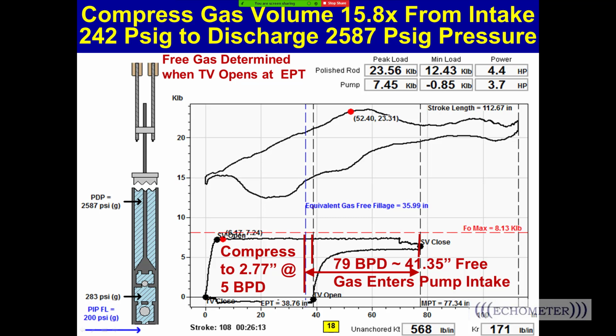That doesn't affect the calculations. Sand is just going to be part of the calculation at the pump. So let's say you make 5% sand, then the liquid volume you calculate at the pump, adjusted for stock tank conditions, should still be 5% too high, because there should be some sand volume that was inside the pump and it was assumed to be liquid, but it wasn't. So it really won't make much difference other than we're going to calculate too large a volume, because the sand also is part of the volume.